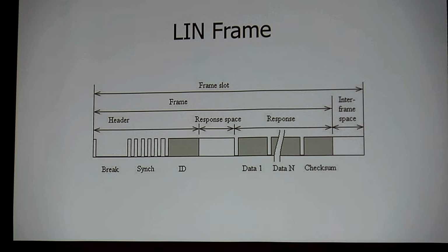So you saw CAN B a lot, and now they've gone away from CAN B. So it's all high speed, except it might be 125 for my low speed, but they don't use that crossover waveform. You'll see a waveform like CAN C, where I'm at 2.5 volts, going up a volt and down a volt, so I go from 2.5 to 3.5 and from 2.5 to 1.5, opposing voltages, okay? So you'll see a wave like that. It's still high speed if it's 125, because that's what the standard says it is. I could run from 125 to 1 meg with this system. So that's what we're dealing with here.